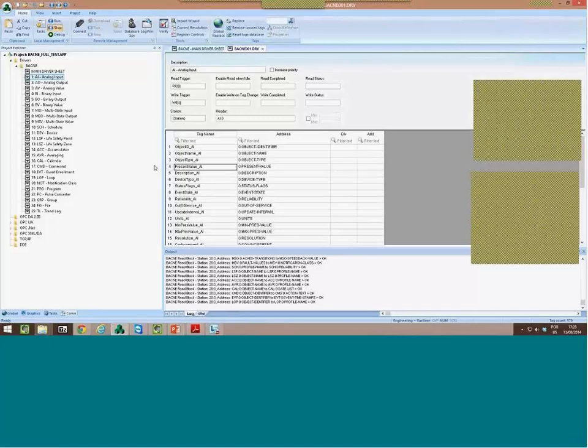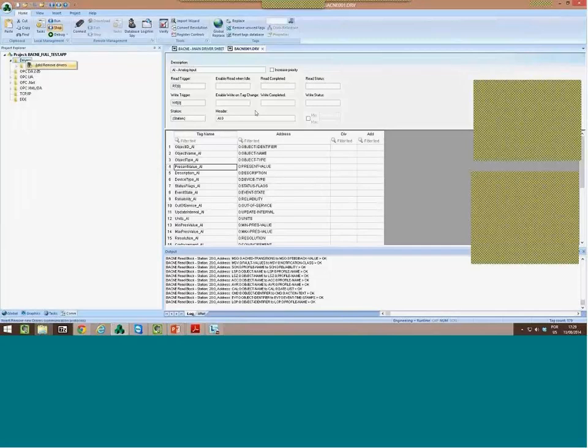a building automation network, right? HVAC network. If you have some sensors that talk Modbus, and you have an entire BACnet network, you can connect them using the InduSoft, right? Using, like I said, Modbus communicating to one of the sensors, and using the BACnet slave to the other part. So you can share data.